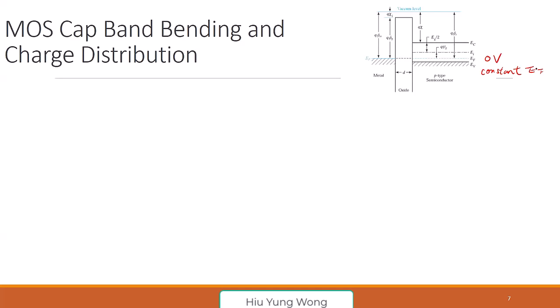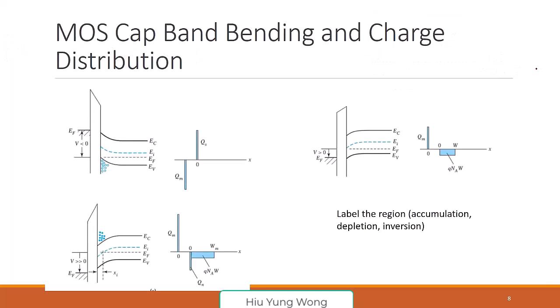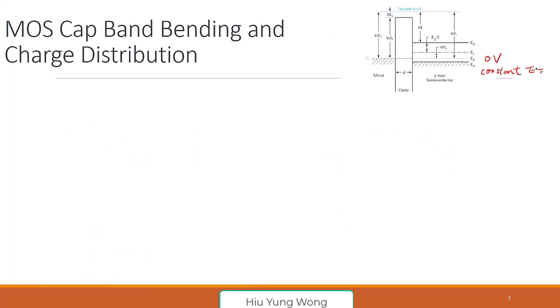Hold on. You just said that it pushes up the Fermi level. Which region? On the metal or on the semiconductor? On the semiconductor, not on the metal. Can you think carefully? You said you input a positive bias, right? Oh, did I say positive? I want negative gate voltage. Oh, it will bend it down. It will push it down, the Fermi level on the semiconductor.